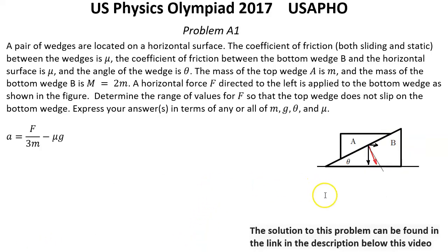In this new frame of reference, this horizontal arrow is the acceleration a, which is going to the right. This vertical arrow is acceleration g, and the red arrow is the direction for net effective acceleration in this system. And now we see that the effective angle will be theta minus this angle phi between the red arrow and the vertical. And we have this expression for this angle.